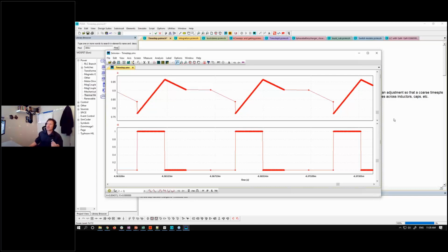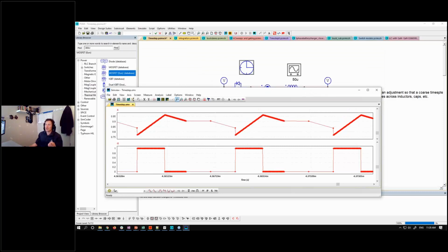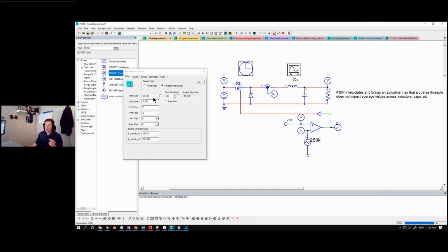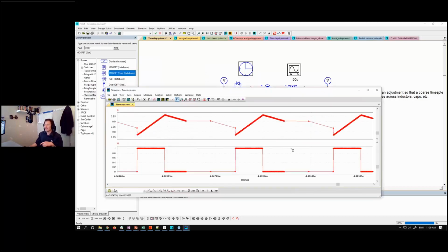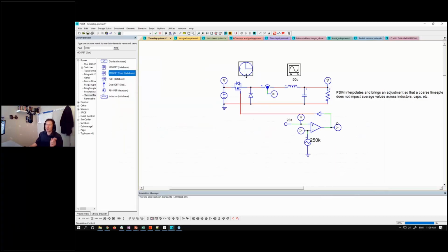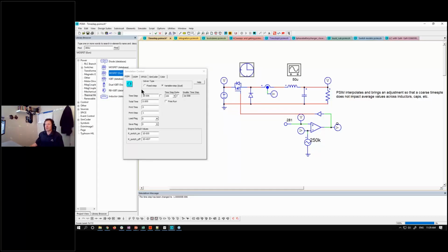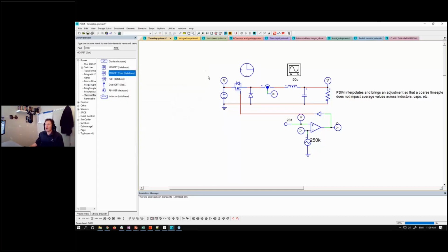These are the sorts of things one needs to understand when using a tool: what the impact will be if you go with really bizarre settings. I was just trying to show a difference there, but that was too much. We need a smaller ratio between the coarse step and the fine step to get that kind of resolution. I'm not going to fool around with that too much because I've got a whole set of other simulations to look at.